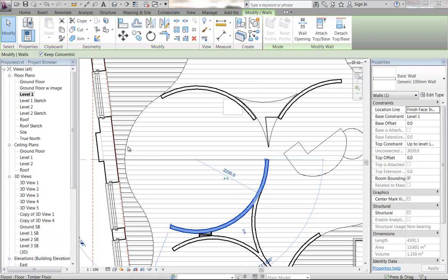Okay, so I'm going to make a new family, and this time I'll set up all the parameters for it to work in both Revit and then also when we're taking it to 3ds Max. So the one I did last week, I think it was just the joinery, and I didn't do any parameters really, did I? It was just the modelling. Yeah, yeah. So I'll go through the modelling fairly quickly, but as I do it, I'll do the parameters and I'll do that a bit more slowly.